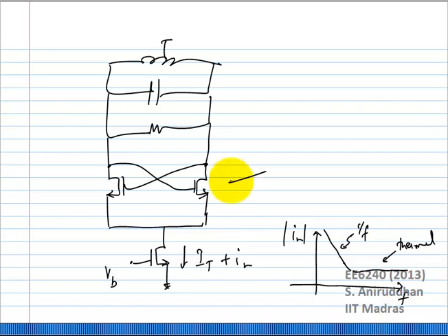So if I actually look at this cross-coupled pair, it's acting like a mixer. If I really had built a mixer, the noise from the transconductance device would go to the output. We have already seen that before. So maybe the noise from this baseband device also goes into the output. That is also possible. Okay.